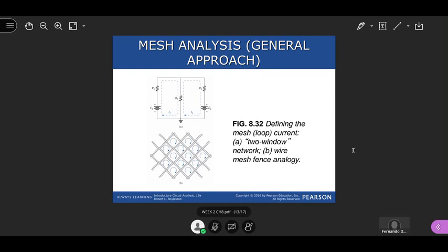I take an educated guess at the best direction to place the current, depending on the polarity and the amplitude of the voltage source itself. Because I want to get as much positive current as I can, meaning that the direction I choose is the correct one. That's it, not because of any other reason. So just for consistency, let's use all of them clockwise, but you can use anything.